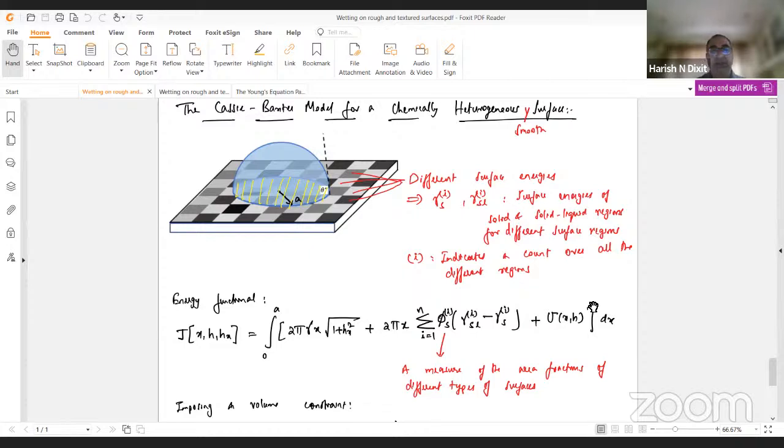You apply a mask and then do chemical treatment so that the part of the surface that is exposed has its local surface energy changed, and then you can repeat this process to generate as complex a surface as you want. It's very common for people to produce chemically heterogeneous surfaces, the easiest being vertical or horizontal strips where the local contact angle is different.